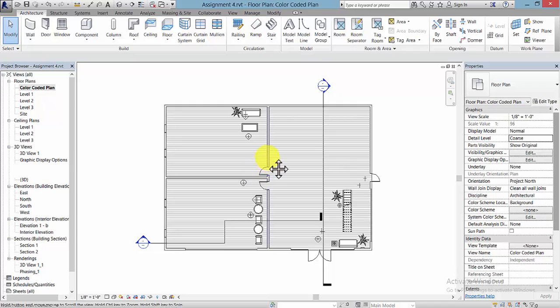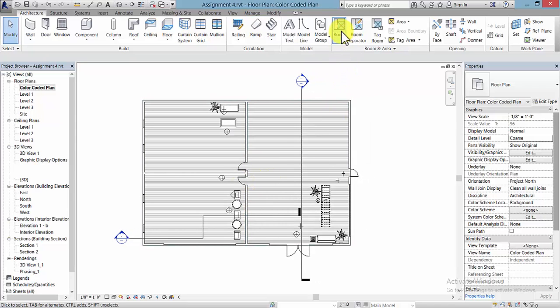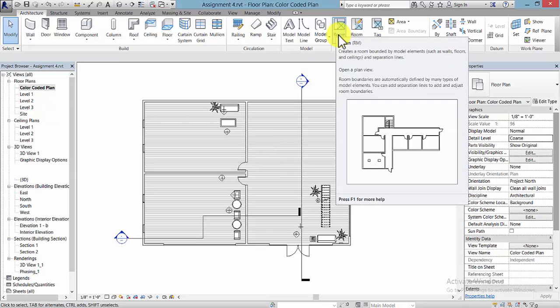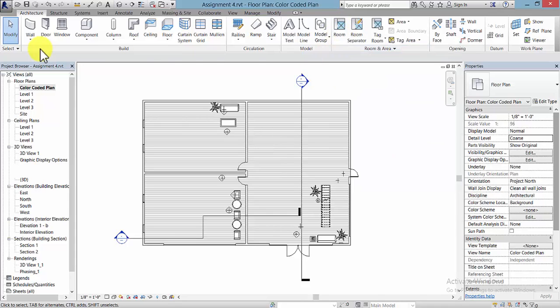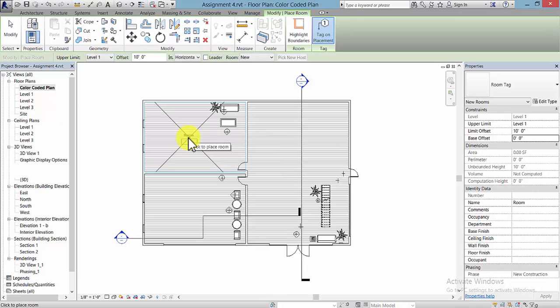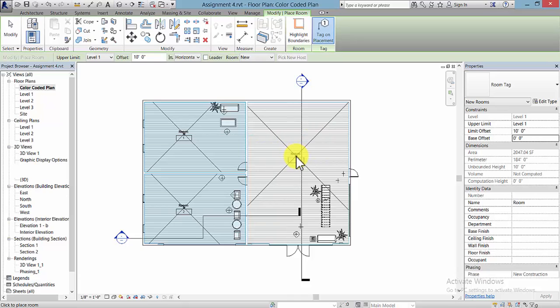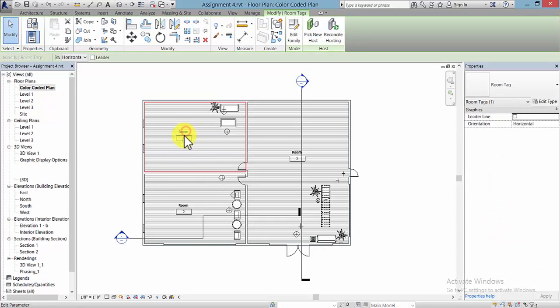So the concept is that we have room tags that can establish here information about that room. So click on, in the architecture panel, click on room, and then go to one of your rooms. You'll see the tag. You could click here, here, and here. This is a smaller plan. And then you can click inside here, this tag, and click again on the title to change the name of